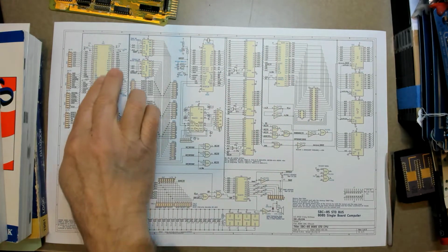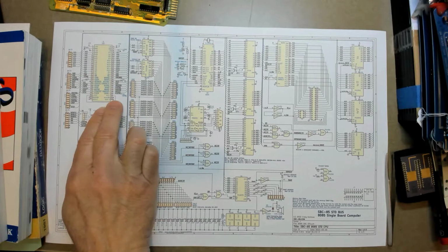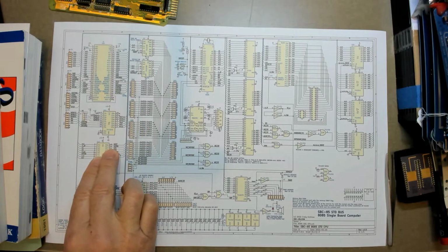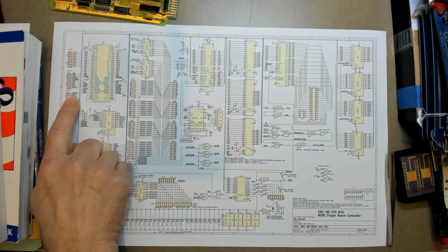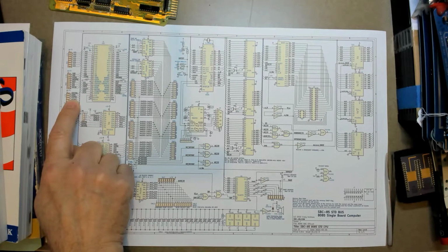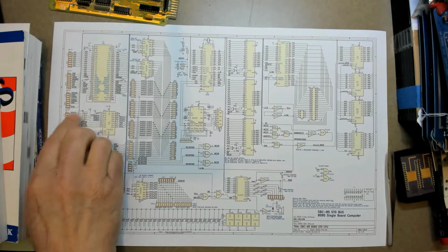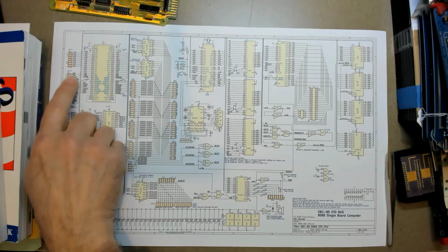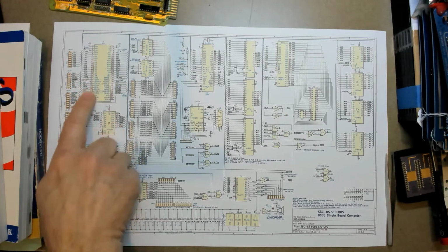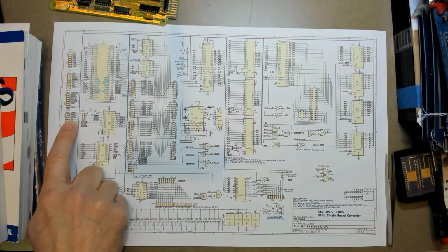The STD connector is shown in the top left. Below that we have control signal drivers, and then up here on the left hand side we have the pull-up resistors on each of the bus lines. For a TTL based interface, these are 4.7K. For CMOS, these would be 10K pull-up. So all of the lines that are coming out to the bus have this 4.7K pull-up.